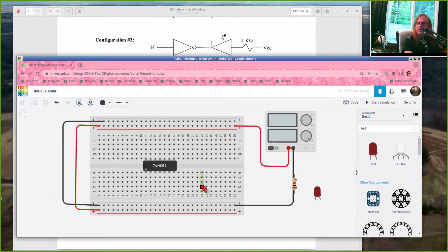All right, so this is always a nice way to start your circuit wiring. Give yourself access to power. All your chips are going to need power. A lot of the other parts of your circuit will need power. So this gives me 5 volts all along here, 0 volts along here, and along here. All right, next thing is the 7404.